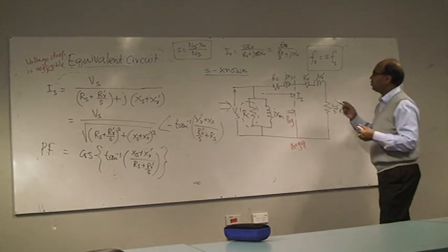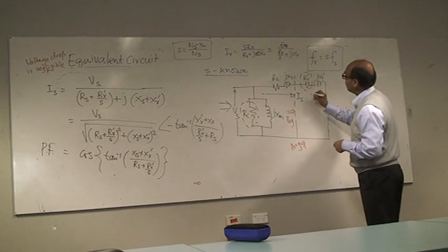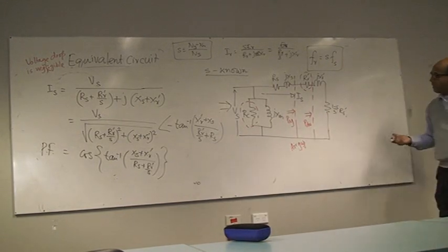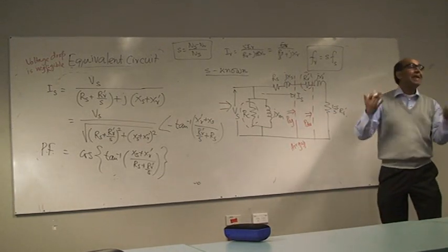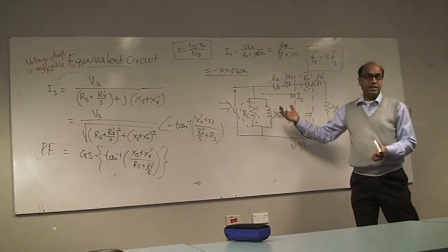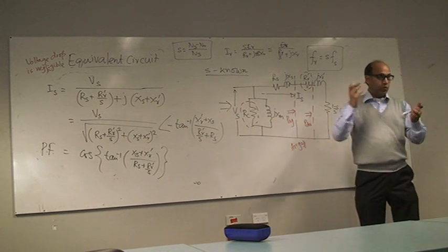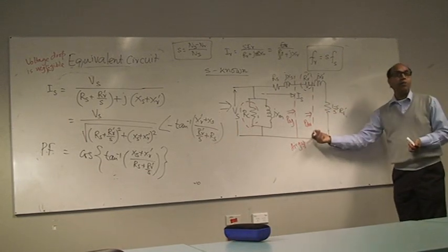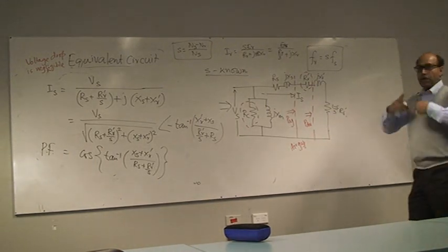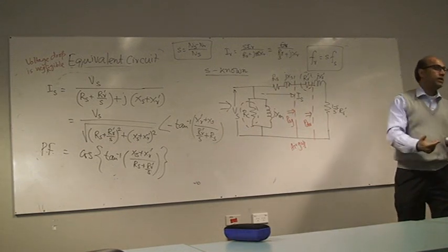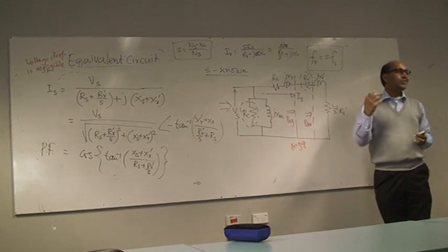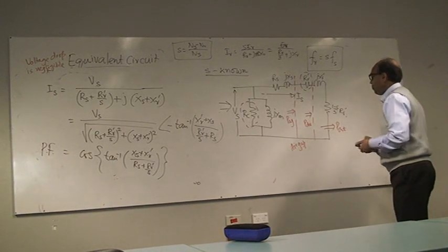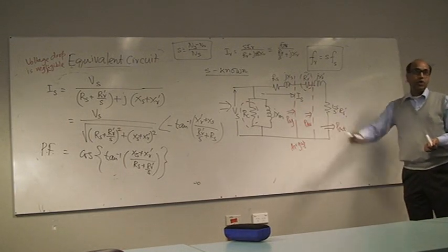After it crosses the air gap, it has to overcome some of the power in the rotor copper loss. Then the remaining power, you call it power developed. What is the meaning of power developed? Power developed means this power is developed into mechanical form, because this motor is nothing but an electromechanical energy converter. It converts electrical energy to mechanical energy, or electrical power to mechanical power. But as the motor rotates, it has to overcome the air friction and the friction of the bearing. So there are some losses which are called rotational losses. From the power you get, you have to take away the rotational losses.